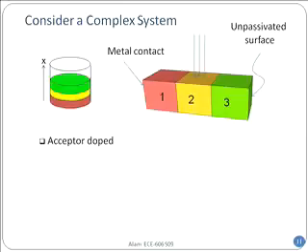The first thing it says, let's say it's an exam problem, is that it is acceptor doped. So you immediately realize that this is essentially all acceptors, and p, the number of holes in the extrinsic region, is equal to Na. That's the first thing you immediately realize as soon as you hear the words acceptor doped.